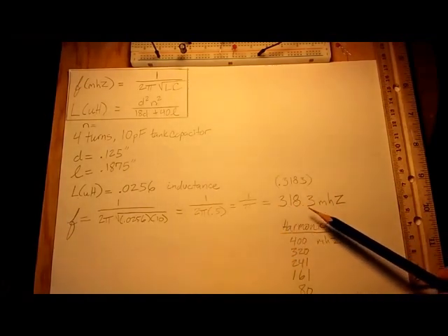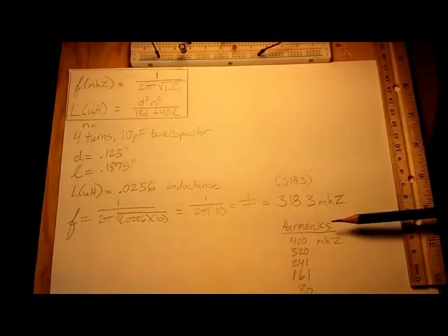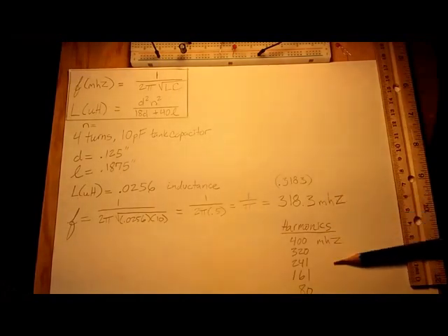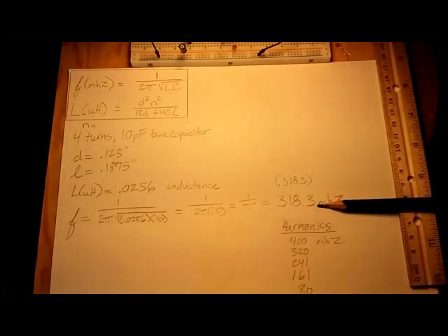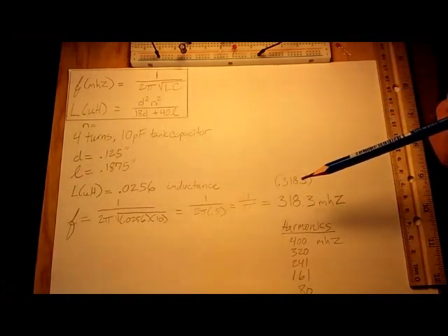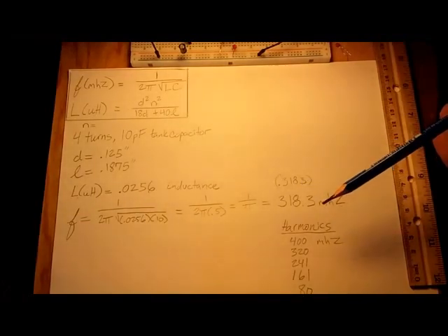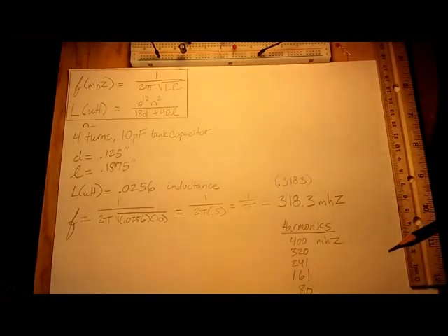Now, before we turn over to the software-defined radio program, what's interesting is that I'm picking up all kinds of harmonics here, you'll see, and I've made some notes previously about where I'm picking up harmonics in the signal. The 555 timer translates as a square wave, and square waves produce harmonics, and they produce harmonics in multiples of the original transmitted frequency. So let's check it out.